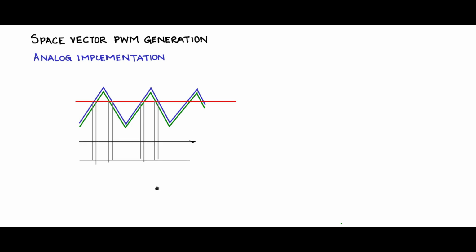And let me have two axes, both are time axes. Let's say one is representing the top switch and the other is representing the bottom switch of one arm of an inverter. So let us say this is the A arm of the inverter, this is the top switch and the bottom switch. For the top switch I will give a comparator, plus minus like this, and let's say I am calling this Vc. I will give Vc to the positive, and to the negative pin I will give the blue triangular carrier in this fashion.